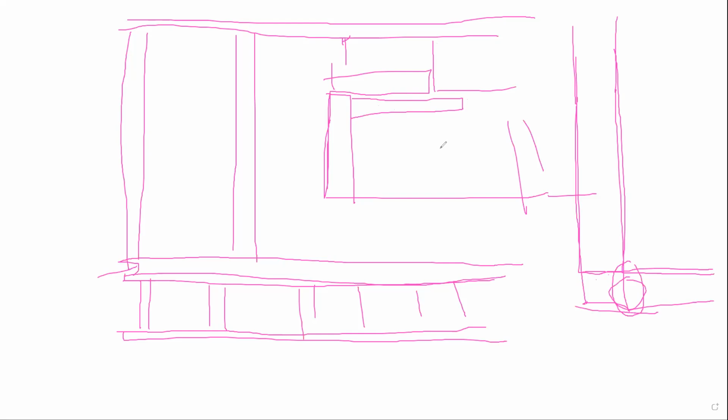So you always make an L in the corner so that when you install the drywall, it has a backing or a support to attach to. A good carpenter will realize that if this wall is going to be up against another wall, he'll just nail the stud here, and that's already part of the wall. This way, when you're ready to do the drywall, it has a backing.